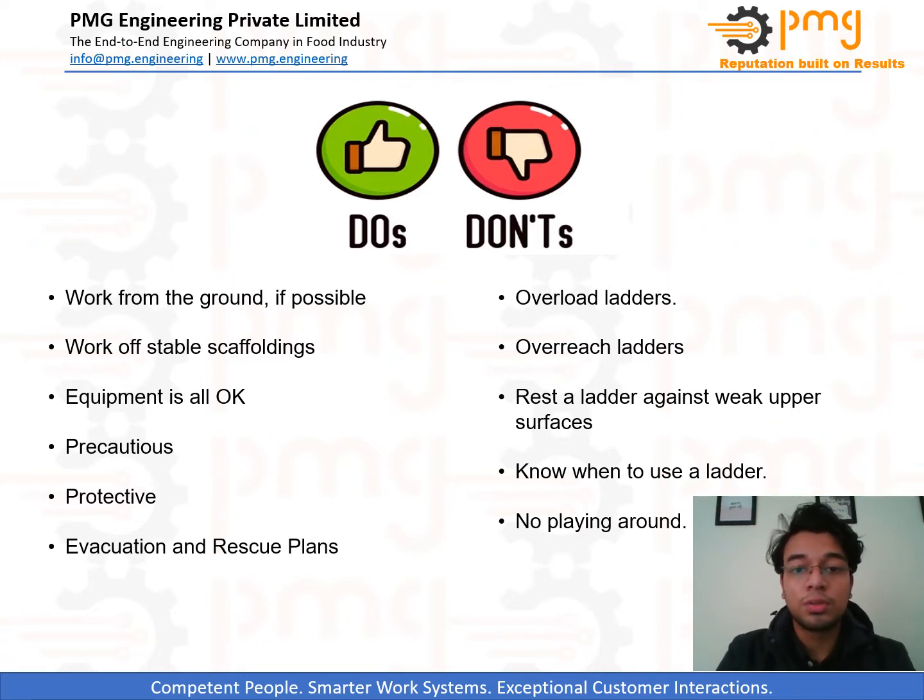Now some don'ts. First, don't overload ladders. Consider the equipment or material workers are carrying before working at height. Don't overreach on ladders and stepladders. Don't rest a ladder against weak upper surfaces, and don't use ladders or stepladders for strenuous or heavy tasks. Only use them for light work of a short duration, and most importantly, no playing around. If someone is not experienced or competent enough to work at height, don't let them work at such height.